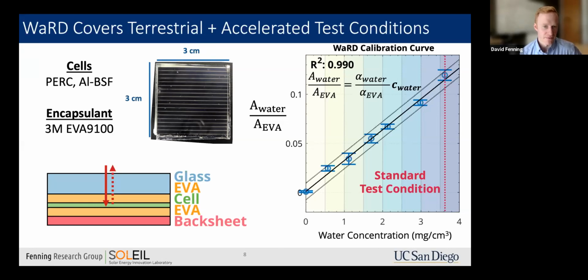So, I mean, we don't have an edge seal, just to be clear. The main effect that we saw was something that we think is unique to the backside of the cells that we had. So the front side water concentrations, because we don't have any edge seal, are effectively the same for our glass-glass and glass-backsheet, right? So any front side effects should be exactly the same. So it's really a backside effect, and the dominant losses were in that generalized, global series resistance, which was everywhere. And so it seems like in these mini modules, there was something, perhaps a corrosion reaction occurring actually at the backside, but somehow that backside was deteriorating in the glass-backsheet.